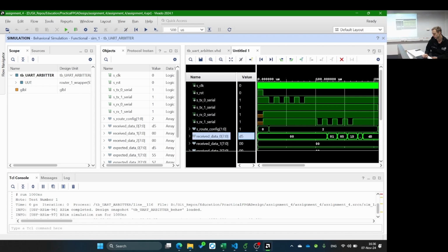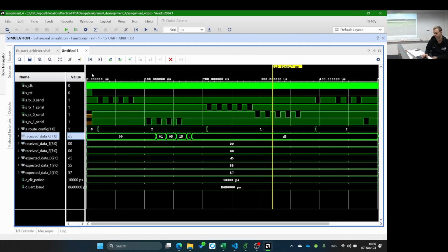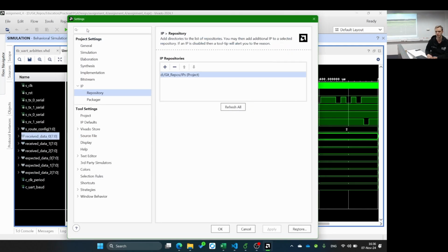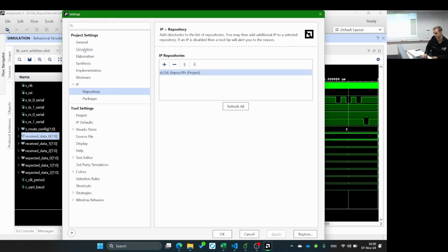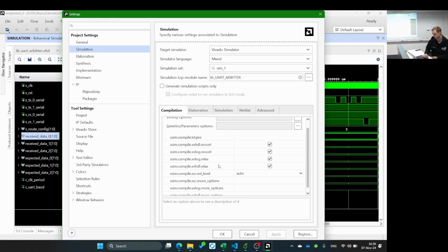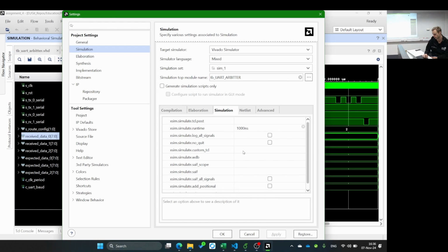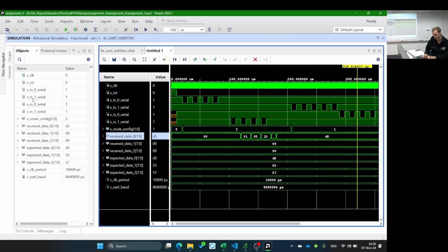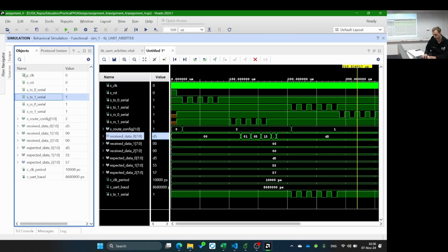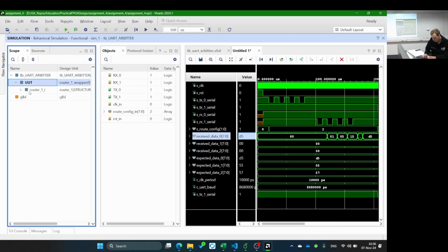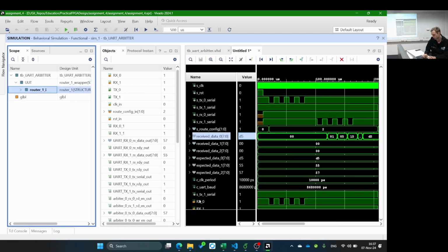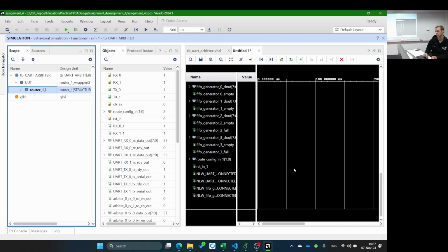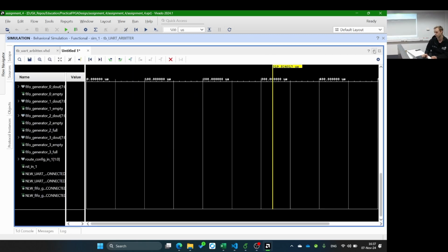For configuration, there are two things which will be useful for you. First of all, the overall simulation settings, which you find under settings, simulation, and then of course simulation again, and there you might want to add log all signals. I will show it briefly, but before that, something quickly. This signal is actually complete. Wait, if we go in here and I load this, I have no signals logged. This might be quite annoying. I've shown this before. I would need to rerun the simulation now.